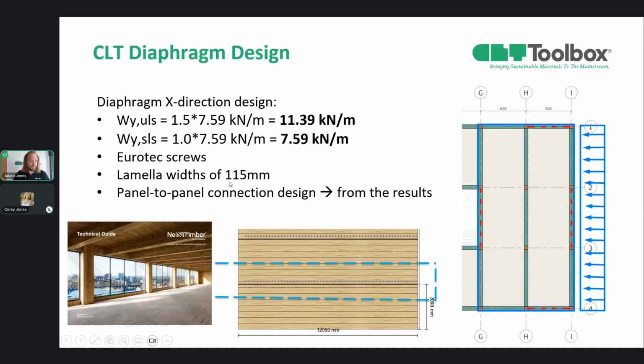And for the lamella width, that's going to be important for the in-plane strength. And that isn't always, well, we don't hard code always the lamella widths, and you might need to speak to suppliers for some of the data like that. So that'll be an input that we get from the Next Timber technical design guide that can be found in any supplier's design guides.